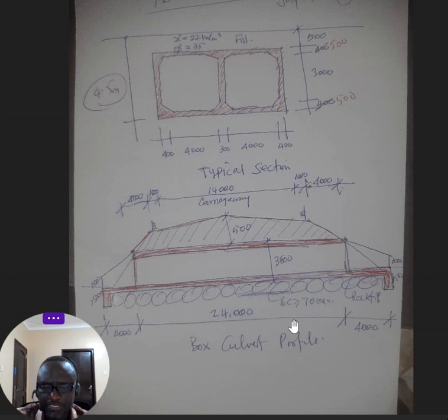Because the rock cannot disappear in the soil. So you do your rock fill from that point, bring it up well organized, laid properly, rolled properly, to avoid dumping rock in a clay content area, which will definitely distort the compaction effect and other things. It can continue settling, and yet your maximum settlement you are allowing here is about 20, maximum maybe 25.